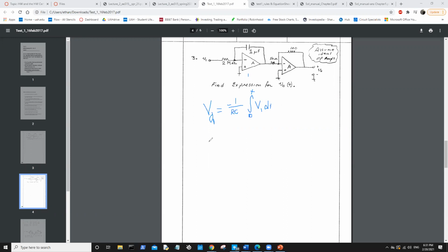And with the other one, you can just use the basic formula that he gives us for inverting amplifiers, which for the v out, v out of t would equal -RF divided by the 50 ohm resistor multiplied by the input, which in this case would be the integral multiplied by VO1. And 50 ohms is from here. Why do we leave out the 100 here? That's RF. Sorry, I forgot that that's RF. When I have it written down on my piece of paper, I labeled it differently than on here. I'm just making sure I don't make a translation error.